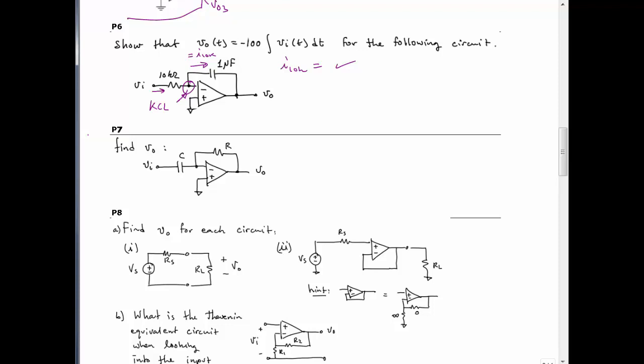And you need to remember something about the capacitor, right? We showed today in class that IC, the current of the capacitor, is equal to C dVc/dt. Right? Well, you can also write the capacitor voltage as a function of current. Okay, and I'll let you figure that out. You'll need to review. It involves an integral.